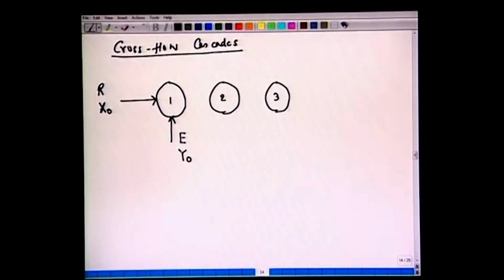Now, if you recall from our previous lectures, when we had the continuous contact process, we said that it is simpler to work with capital X and capital Y, which is solute free basis. If we have binary components and only one component diffuses from one stream to another stream, then it is convenient to work with capital X and capital Y mole fractions as well as the molar flow rate on a solute free basis, because we realized earlier that operating lines in such cases become linear. So, our mathematical computation becomes simpler. Here also we will work on solute free basis mole fractions, solute free molar flow rates or mass flow rates.